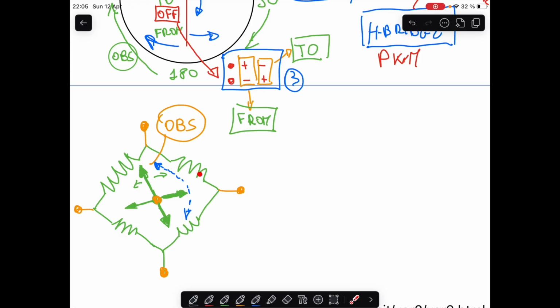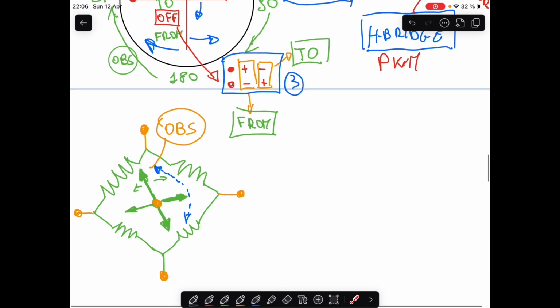And these resistors are 90 degrees apart here inside this compass. So we're going to measure 4 different values each time at each position of the OBS knob. And thanks to these 4 values, we're going to be able to reconstruct the sine and cosine components of the OBS. With a little bit of math, it will be easy to reconstruct the angle, and it will be quite straightforward, after having a sine and cosine, to get the angle out of it.